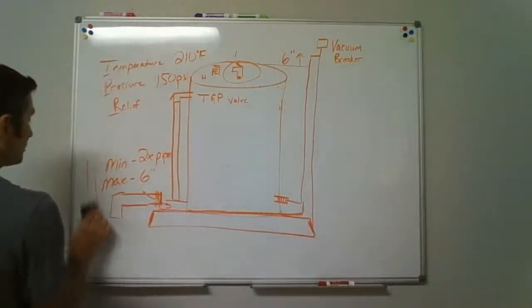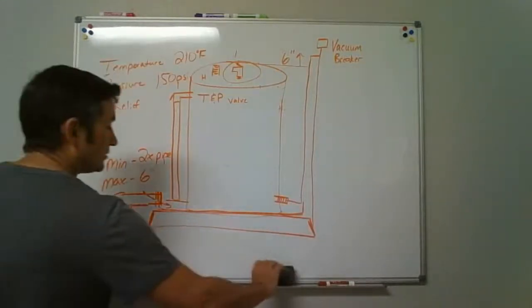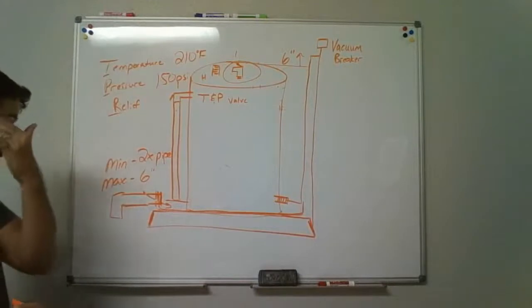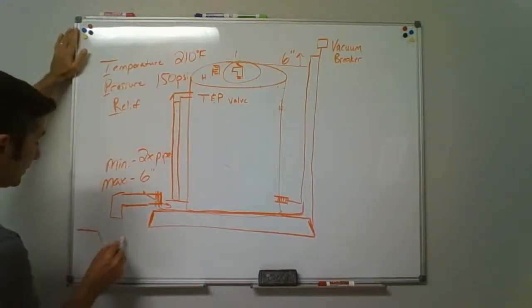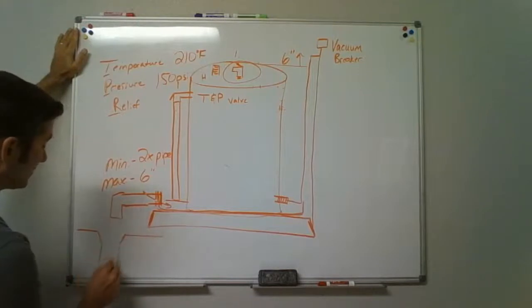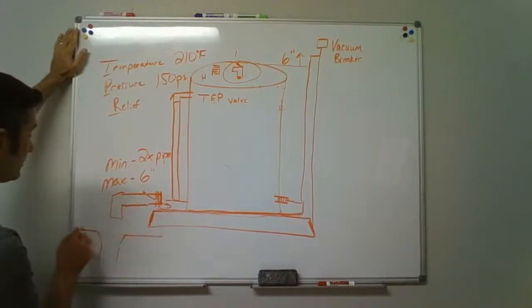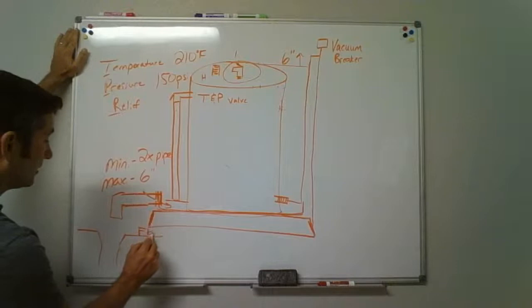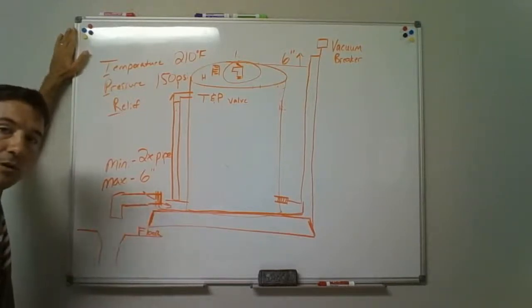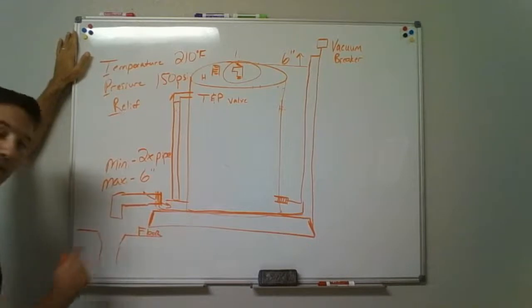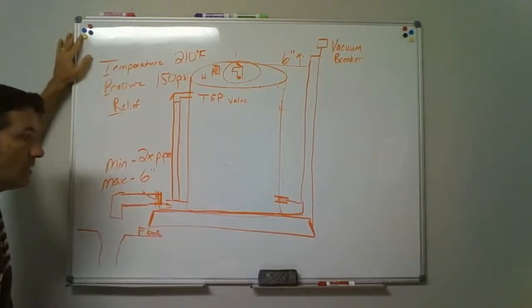It says that this can just discharge into, let's just say you were putting one in and the room had a floor drain, and that went down and had a trap underneath it. This is the floor, and you had a floor drain here. You could just pan it over onto the floor and let it discharge onto the floor and it'll run into that floor drain. That's fine.